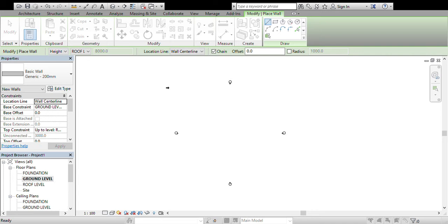So you can click here and click insert. You insert materials on top of that block wall, and put thickness. For example, I put 25 millimeter thickness, and then I put materials. I click by category, click here. So the material browser will open. So I'll select the materials of the wall to be put outside.